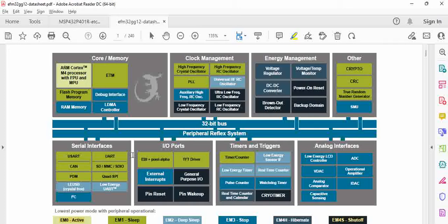So you can keep the microcontroller active, and then you can take it right down to the shut off mode, and you can save a lot of power. So there are IoT devices in the fields which work for 3 years or more with a simple coin cell. So this could be one of the options, but again, we need to do a lot of power calculations for that. You can try it out and see,